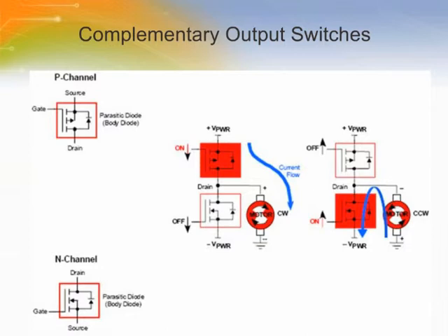When a P-channel high-side and an N-channel low-side power switch are configured as shown, the circuit can be referred to as a common drain half-bridge, since the drain terminals of both switches are tied together. More commonly, when the two switch elements require opposite polarities of input voltage for turn-on, the combination is said to be a complementary output switch. The advantage of the complementary output switch is that control circuitry is simple when complementary power supplies are available.